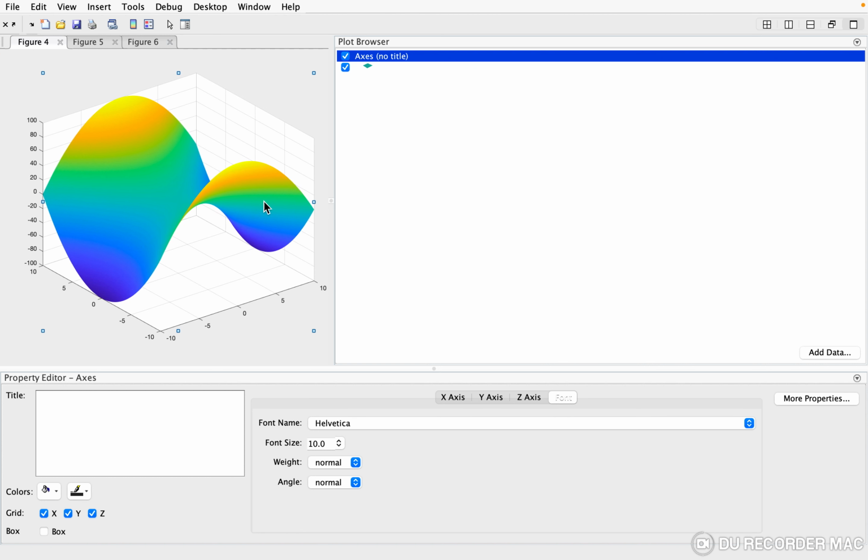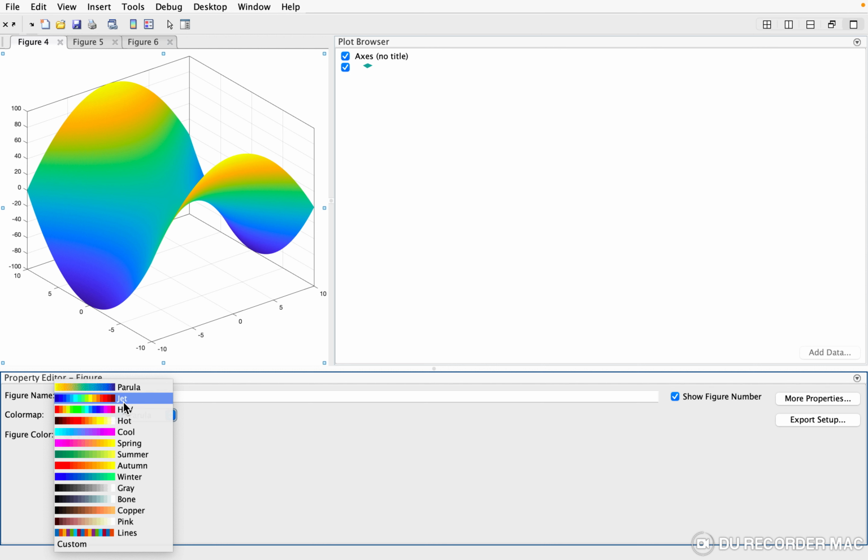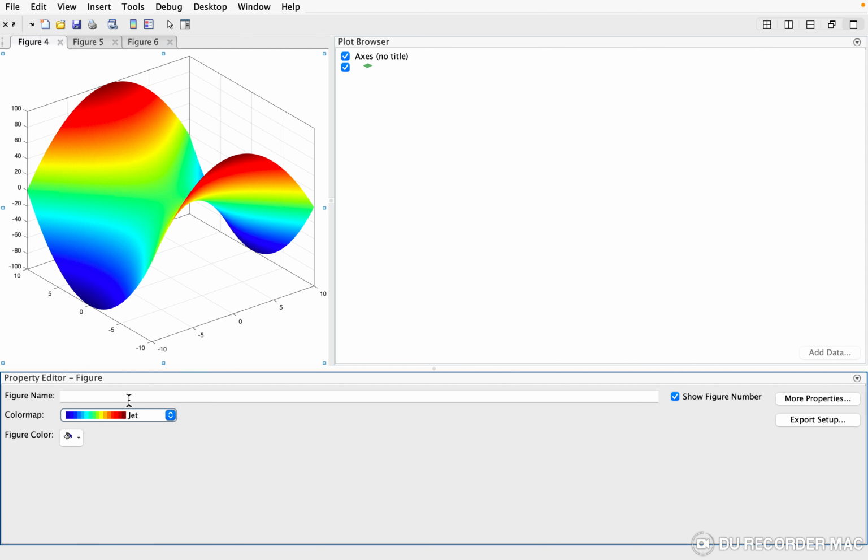Then here you have color map also. In this color map you can use different things. The best thing for any plot would be, unless you are working in something like thermal things, then you can use the hot figure or autumn figure in this kind of things. But if you are using something like fields, particularly I am working in electromagnetics, particularly in wireless power transmission, so I will use jet.